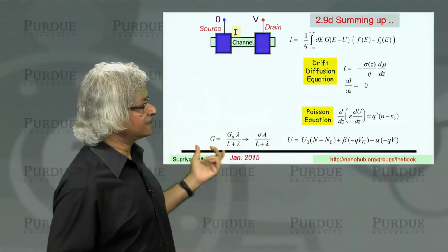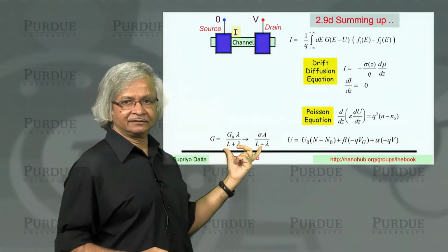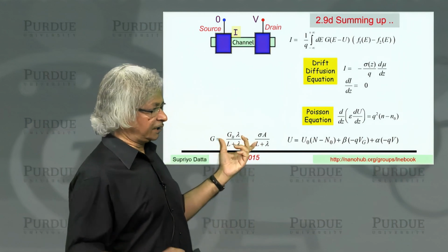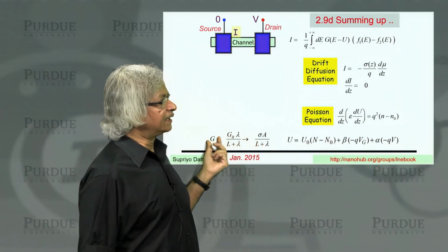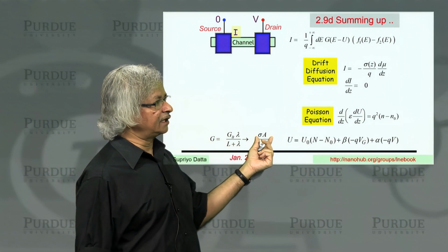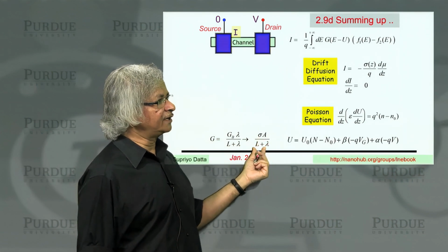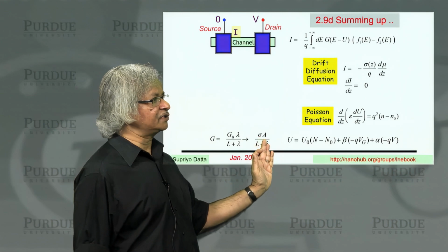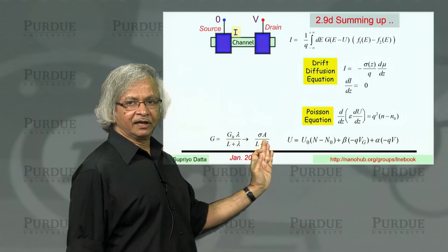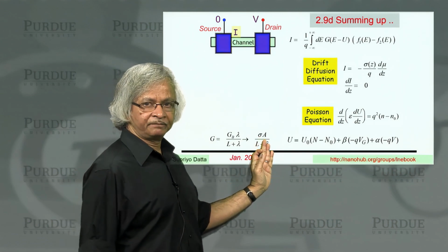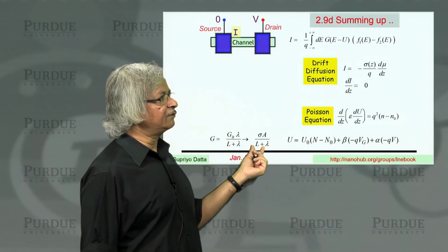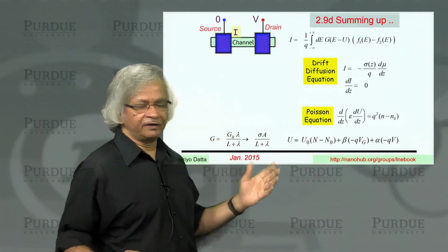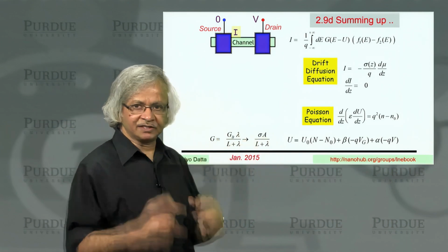What I mean by that is, you see the expression we got in the last few lectures and the last unit, that the conductance is given by conductivity times area divided by L plus lambda. Whereas what you'd learn in freshman physics is usually sigma A over L. That's the usual Ohm's law. What you have seen is, even when the length tends to 0, the conductance doesn't go to infinity, but rather goes to a fixed number.